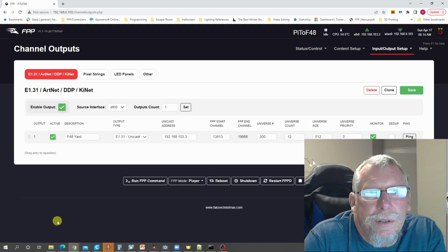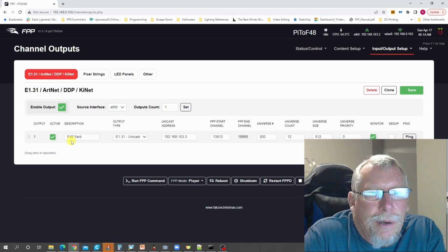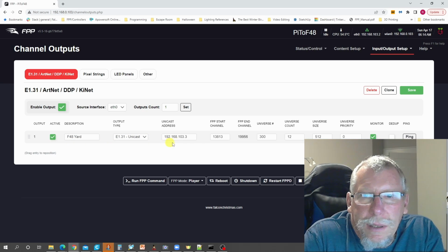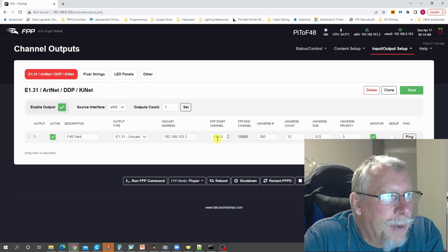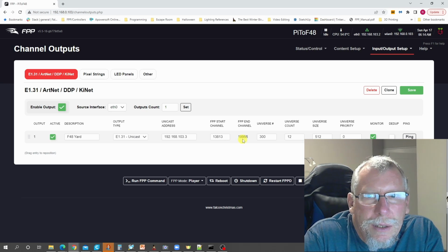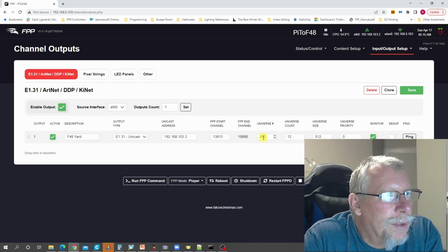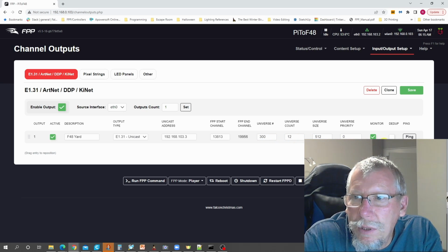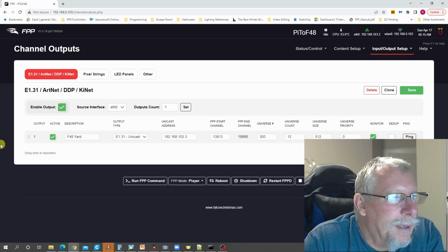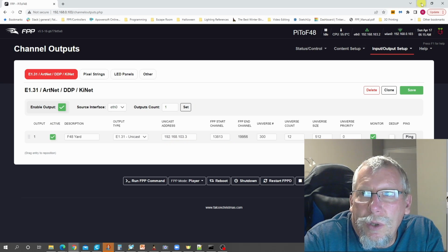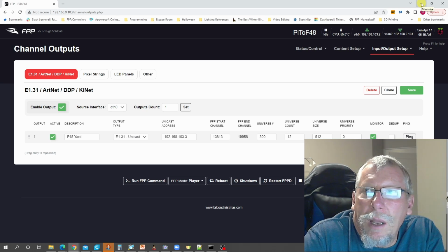So we'll refresh the screen. And you see now here it has the F48 unicast. Let's see, the start channel 13813 is correct. The end channel 19956 is correct. Universe 300, 12 universes, 512 channels per universe. So that looks good. So you see that the FPP Connect does it correctly.